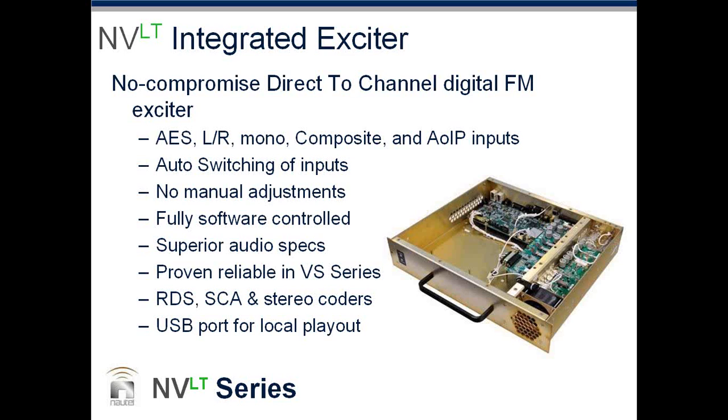So any exciter needs to have RF power capability to drive those modules. Right. So we use the exact same RF amplifier, this LDMOS 800-watt device, and you can see that on the right-hand side there. Yep, that's over here. Right, so the exciter output off the low-level card comes out at a few hundred milliwatts, drives that two-stage PA, and then that drives the rest of the transmitter.